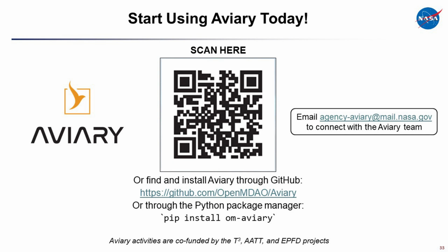For example, if you have a bunch of different engines that use electric power, Aviary is just going to hook them all up to some sort of sink that accepts electric power as an input, like a battery, and the battery is getting a request for how much power to get. It'll just assume that connection. It won't understand if you want to do a split. Oh, I have 3 different kinds of batteries that want to be used different ways. That's not something that it'll understand out of the box. You'll need to do a little bit more tinkering to custom set up a power flow. Okay, very good. Thank you.